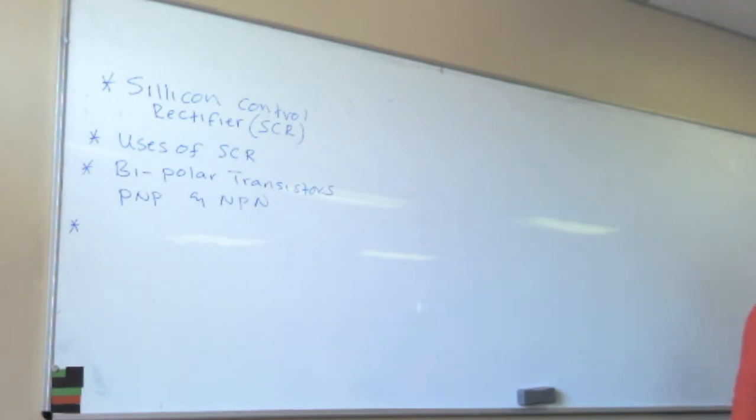Yesterday we discussed diodes and their uses and the types of diodes. Then I went on to discuss the schematic presentation of a diode and then rectifier circuits, because diodes are used in rectifier circuits. And I said the rectifier circuits are used in battery charging systems. So they can ask you for a 1 diode circuit, a center tap transformer with 2 diodes, or the other one with 4 diodes, which is a bridge circuit. And I explained nicely, so you'll be able to answer the questions if ever I ask questions in the test or in the exam.